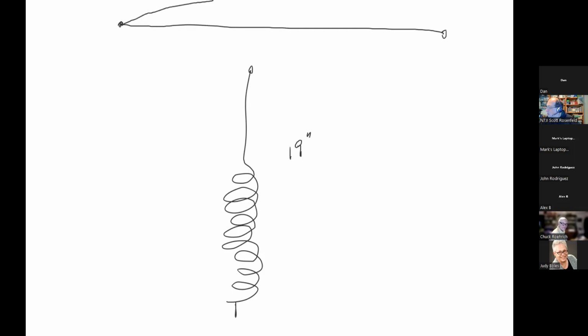Current at the end has to be 0. Well, this is a quarter wave antenna, which means it's actually half of this, which means that the current is at its most down here. And if I started to draw that wave, it goes like this. But then what happens in here? My peak gets big really fast because it's all short, right?